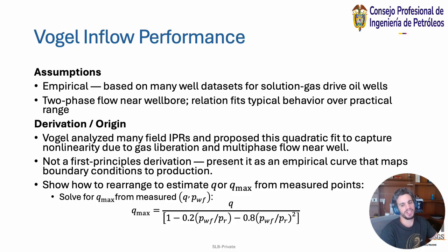So essentially, it's based on shape-fitting curves, right? Based on the data sets for the solution gas drive. And you use this inflow performance equation in nodal analysis, in well modeling, and for predicting the effect of artificial lift, right? So for your different methods of artificial lift, you want to measure that performance, or whether you were able to achieve the objective or not. And it is entering the mathematical space of nonlinearity, which Darcy is not able to do successfully, right?